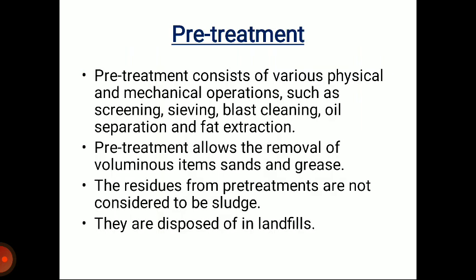Pre-treatment consists of various physical and mechanical operations such as screening, sieving, blast cleaning, oil separation, and fat extraction. Pre-treatment allows the removal of voluminous items, sands, and grease. The residues from pre-treatments are not considered to be sludge. They are disposed of in landfills.